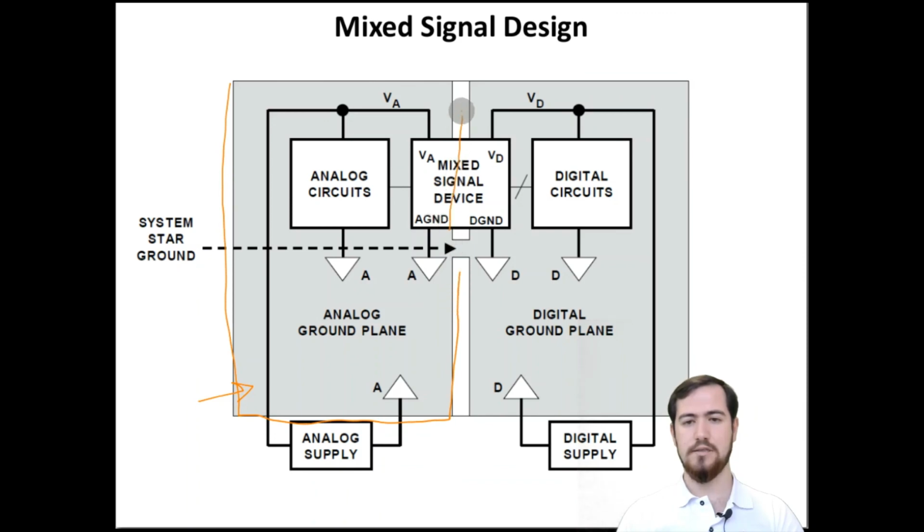Here the analog signal operates, and on the right hand side the digital signal operates. As you can see, the ground levels are actually the same, and these are connected to each other. Let me draw it, connected with a very tiny amount of copper.